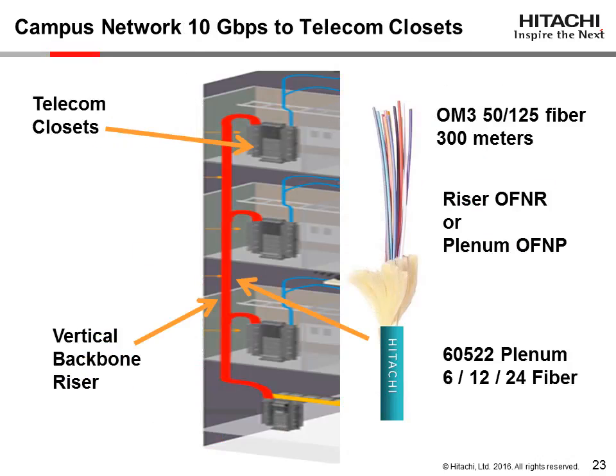Once in the building, the second most widely used application for fiber optic cables is in the vertical backbone riser. In this application, fiber optic cables provide the interconnection between main data network cable coming from the equipment room to all telecommunication closets. The telecommunication closet contains the connection equipment for workstations in the immediate area, cross-connecting to the equipment room and to the horizontal wiring connections leading to the end devices.